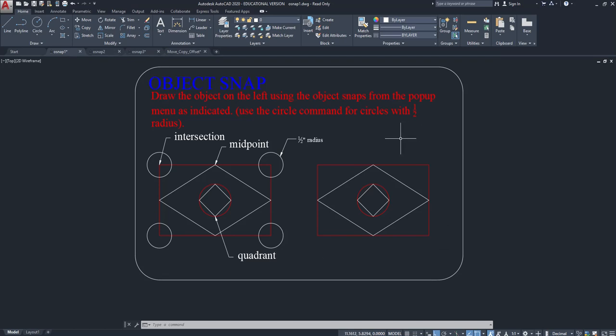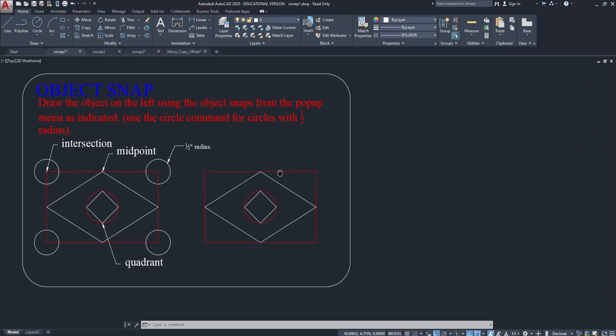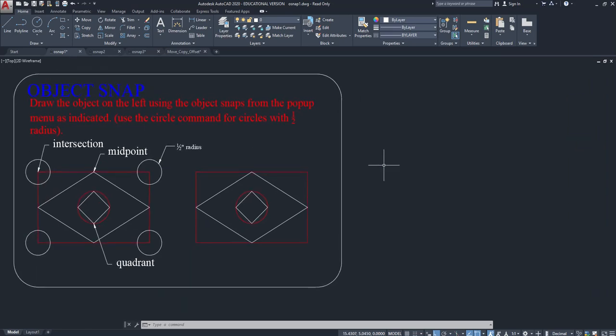what happens if I want to create a line that's dimensional, right? What happens if I want to create a line that is 5 feet long? The first thing I want to introduce you to is the idea of units in AutoCAD. Down here in our object snap toolbar as well, we have this area. It's called the units drop down or setting, right?